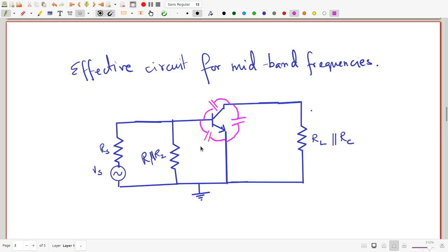So it's easy to understand why you have these effective capacitors, the base emitter, the base collector, the collector emitter capacitors, which are all things which will divert current away, which will provide alternative current pathways for current to flow away from the active path. Also, as far as the output is concerned, any current which goes through this path does not go out into the load. So all these will negatively impact the working of the transistor as an amplifier.